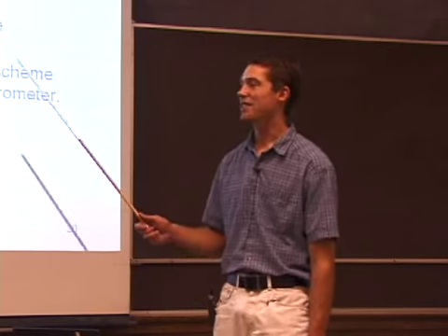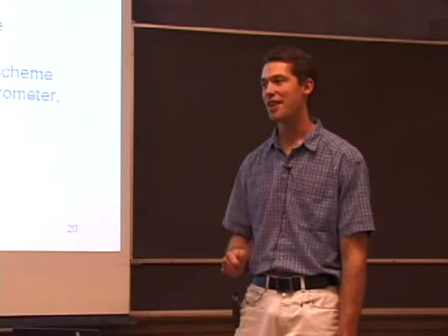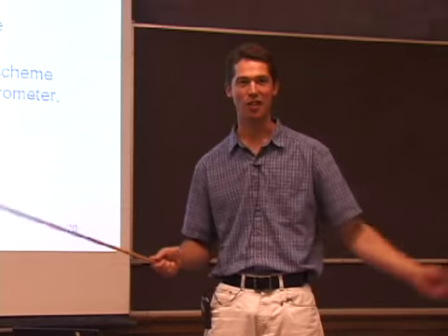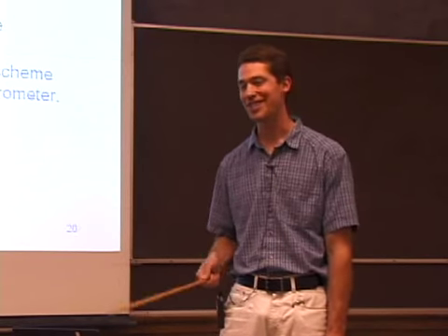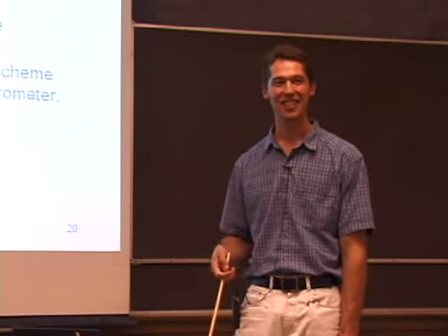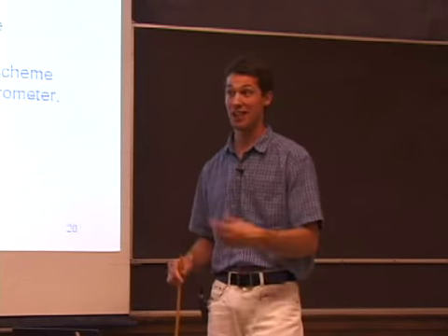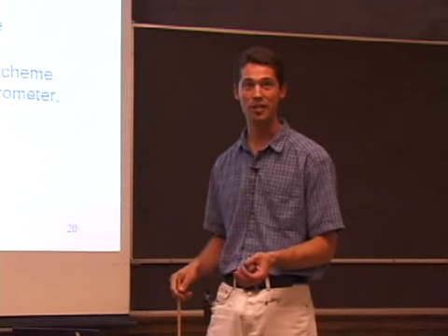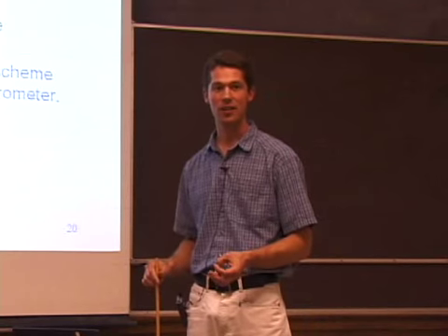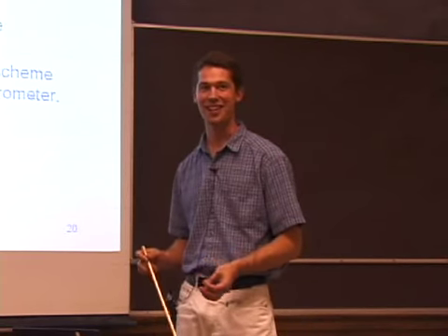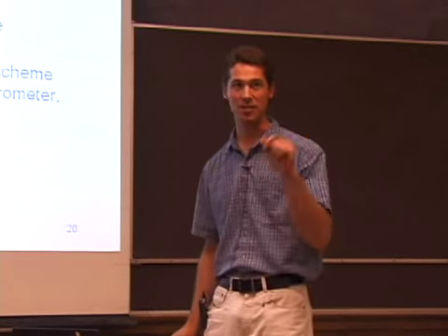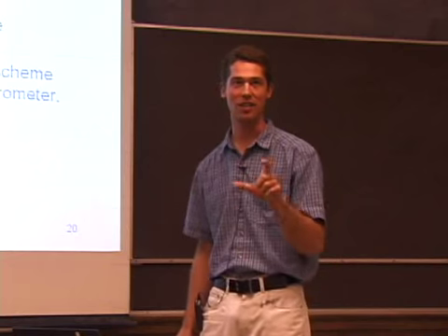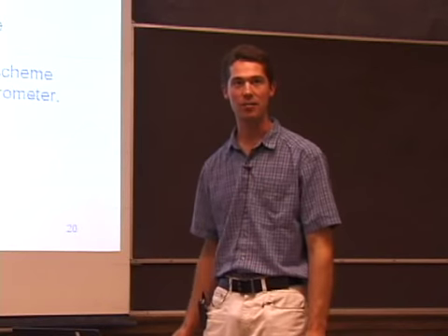One way to think about this is if you think about a sensing matrix and you say, okay, let's start out by designing a sensing system which has a diagonal matrix. Then a lot of your problems go away because inverting diagonal matrices is a very easy thing, right? So if you come to that conclusion and have a way of doing it from the beginning, that's really great. That would be thinking about it in the design phase. Exactly. I looked at some of the sensing schemes, and if you can really just make your sensing scheme inherently diagonal, you've got a much easier job.